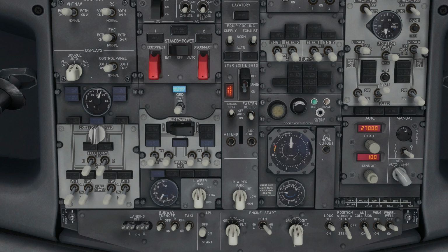If you don't turn on the APU engine gens, so N1 and 2, what will happen is if you try to start them without anything, you're going to see a total blackout. But if it does do that, just basically turn the APU gen back on, and it'll all work fine again.